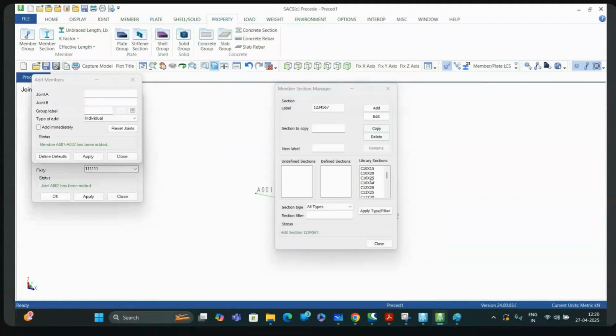Now if you come into the section library, there will be some section libraries. So if you want to select a wide flange from here and apply filter, you will have different types. So look at the requirements from the client and select which one you need. Now I am selecting a W10X. And if you select directly like this, it may be hard for me to get it.